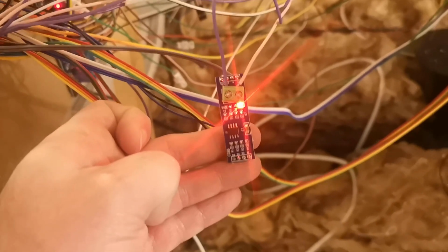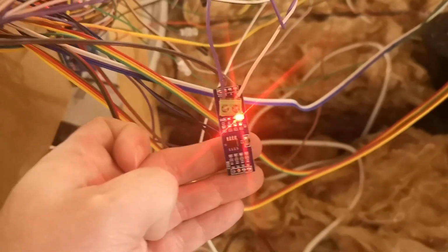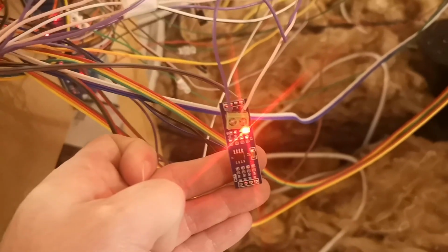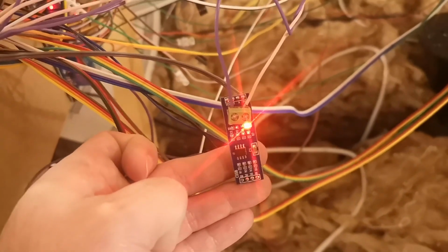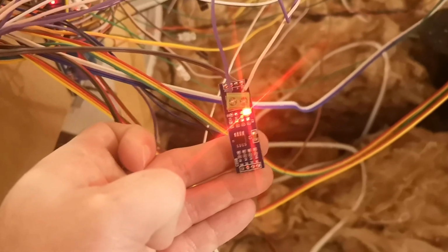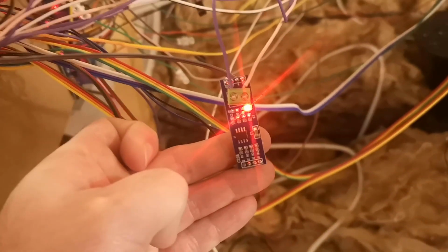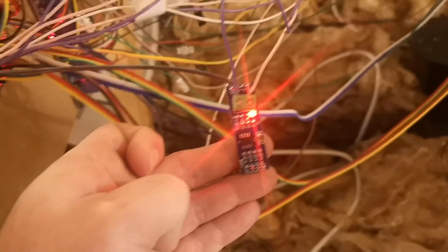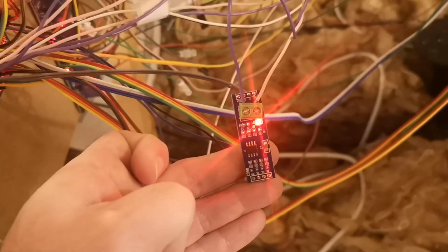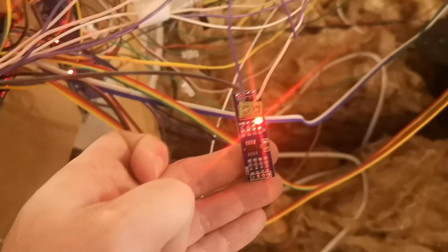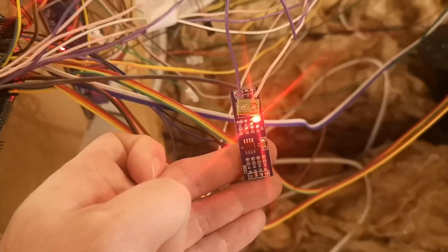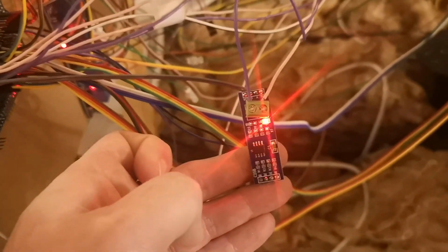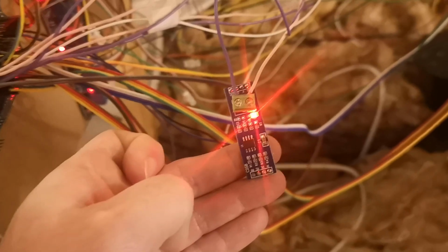However, it hasn't always been a smooth ride for me with RS485, and I could put plenty of card links to other videos to underline that. The main problem I have is these Max 485 modules seem to expire quite quickly, and when they go, it can be quite a complicated process because they seem to be able to take other RS485 modules on the bus out with them, and it can take quite a long time and quite a few of these modules to get it all settled down again.